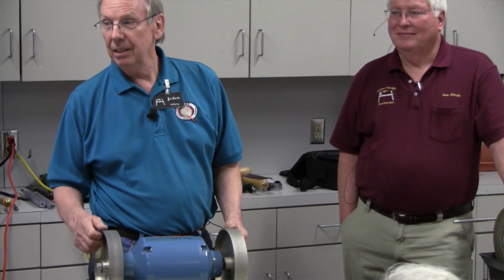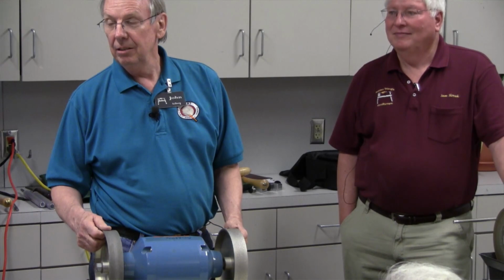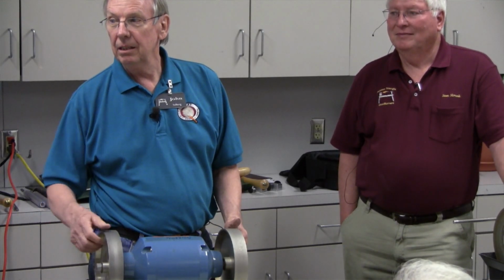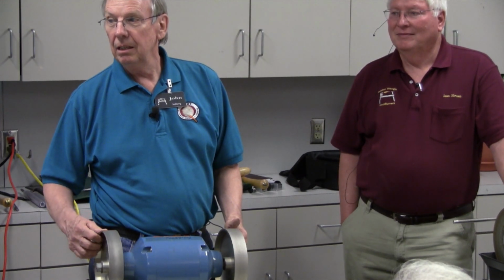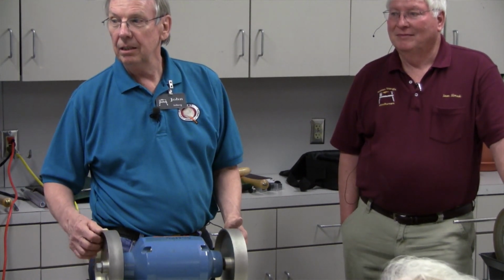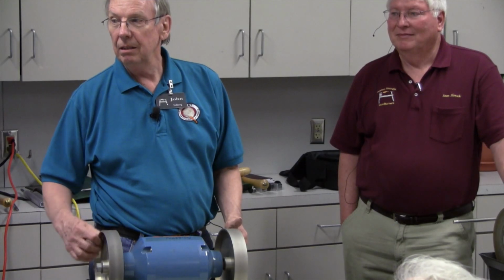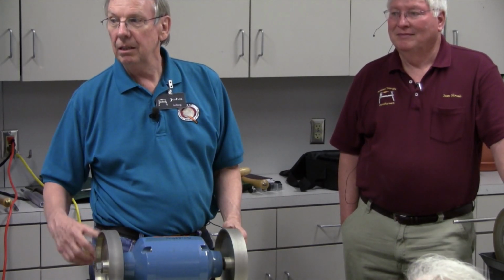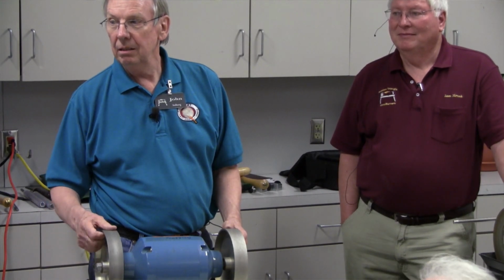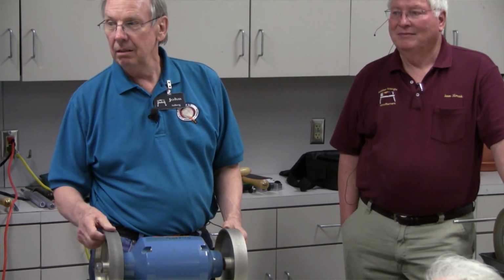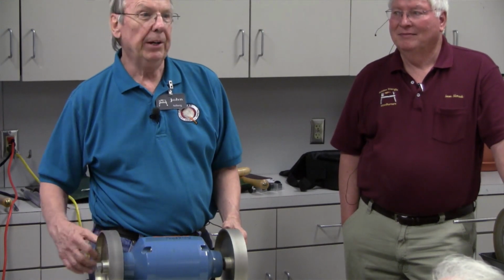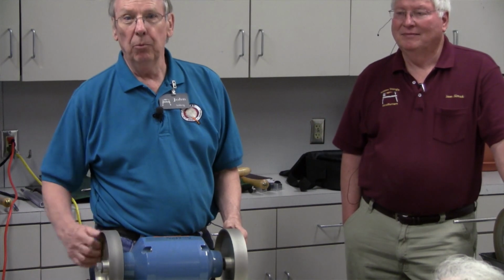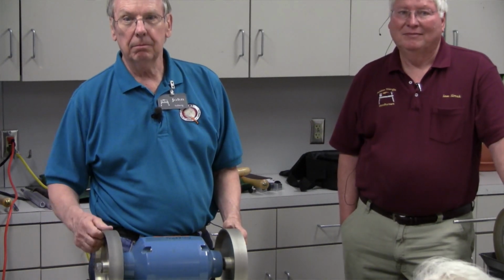Stuart, Alan Batty's little book on wood turning notes shows three different examples of grinds or sharpening. For soft wood, you would use a more narrow angle. For the medium, it would turn out to be about a 40-degree angle. And then for very hard woods, you would have the angle more flat. Everybody hear that, or do I need to repeat it? For hardwood, you'd want a more flat, steeper angle.